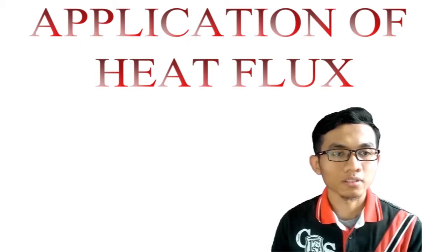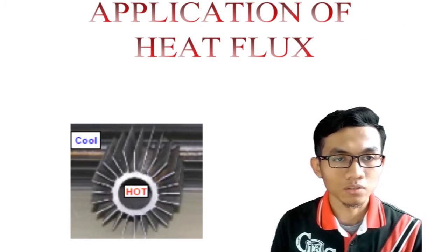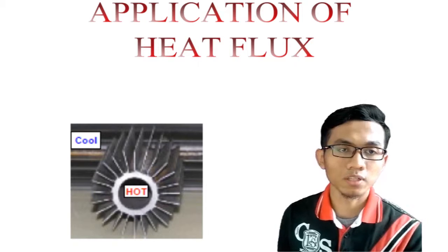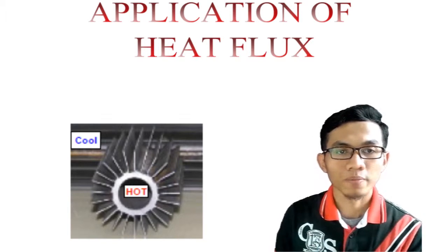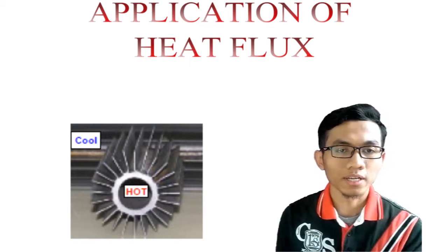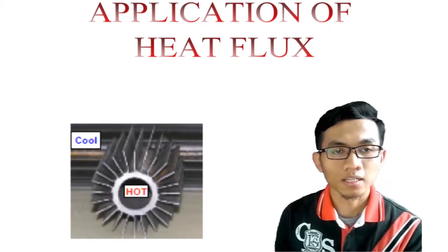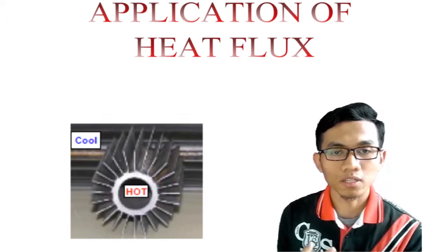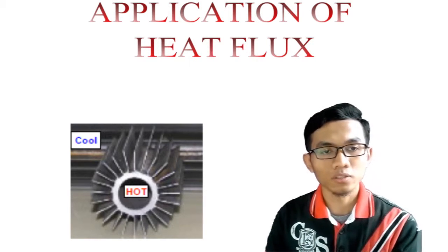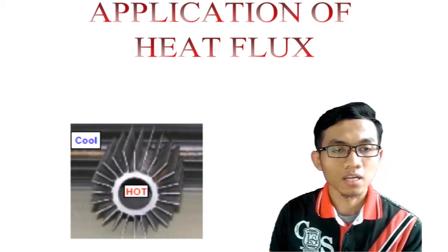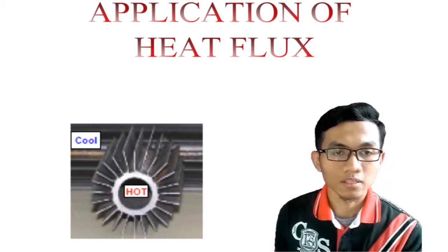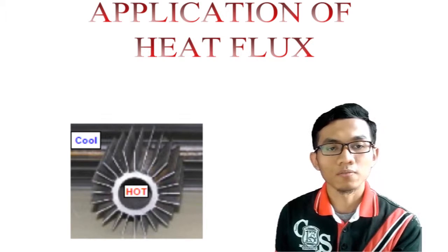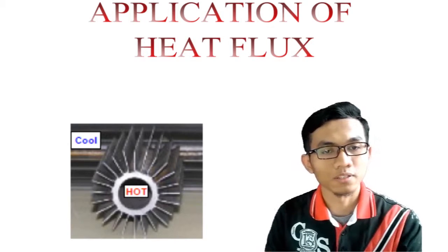Here is a picture of a tube with longitudinal fins, which are in common use. You can see there is a cool area and a hot area. The heat inside the tube will flow along the plate fin to the cool contacting plate outside. It is desirable to analyze how effectively heat can flow in a cross section of the fin.